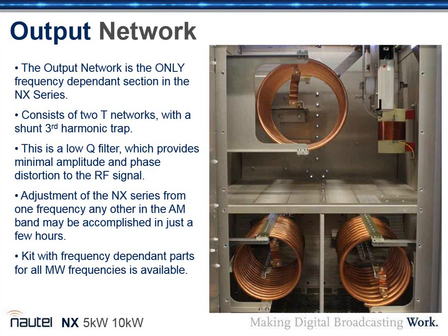And this filter has been updated a little bit to make the tuning easier and more consistent. So we've added some bars. You can kind of see them. This one's probably the easiest one to see. There's a bar that comes out here, and there's a clamp. And that means that the little flexible strap that's usually in these kinds of inductors is very short. Yes, and it makes it, as you said, much more consistent in the way that it's tuned.